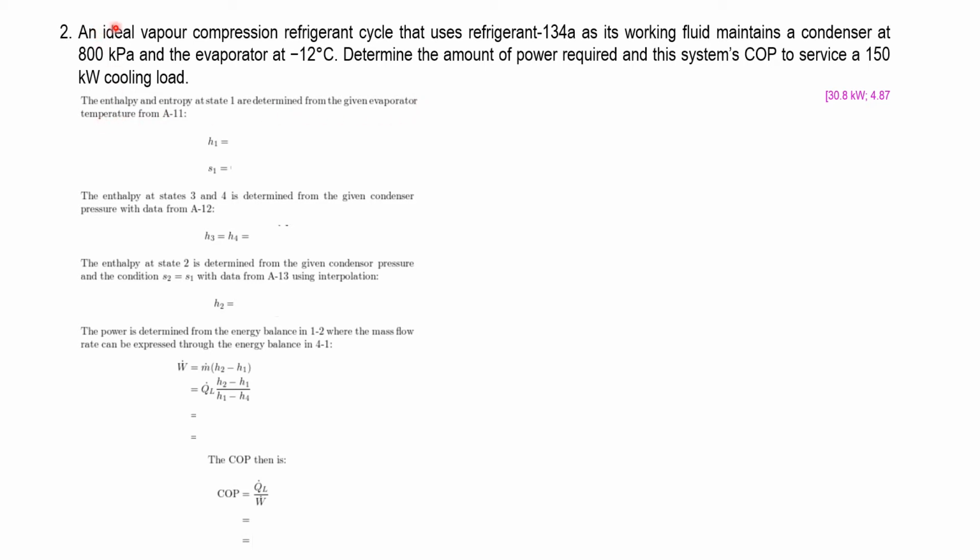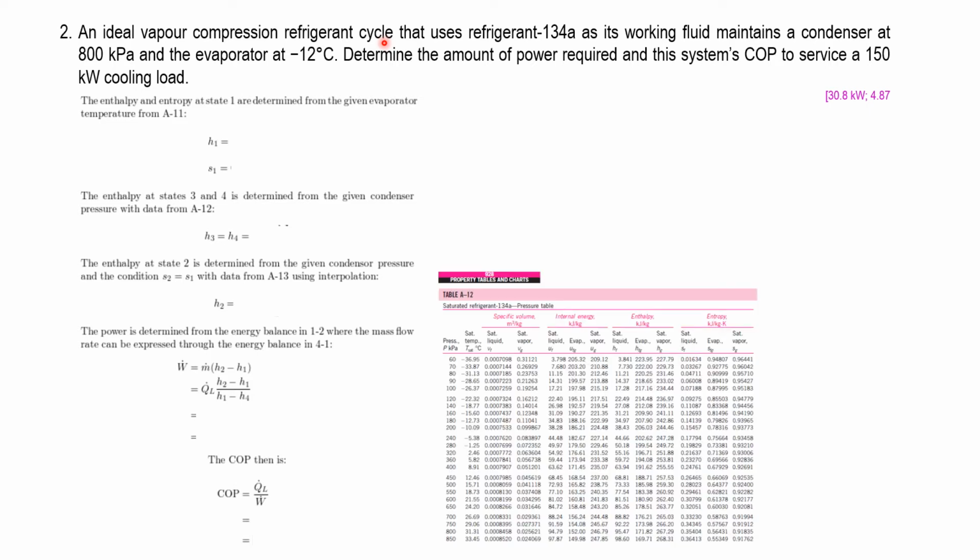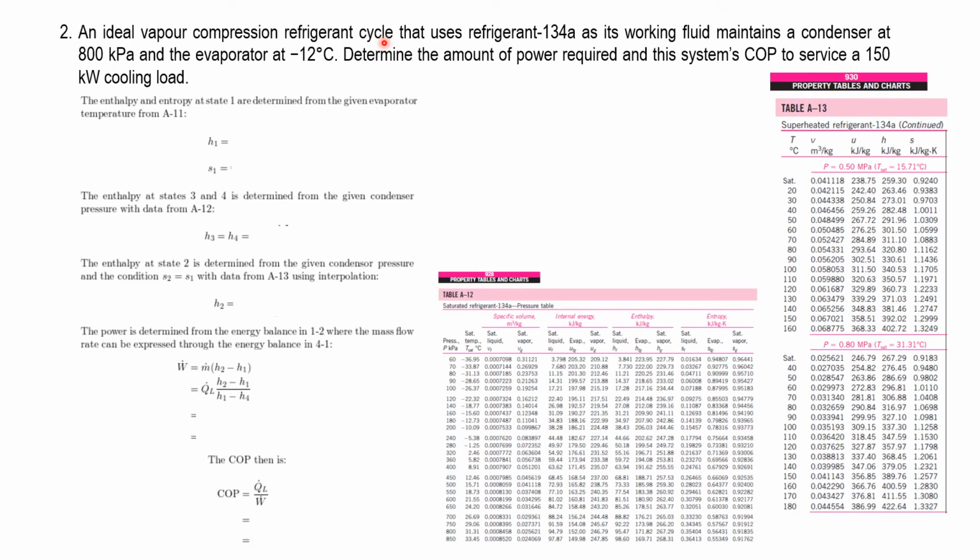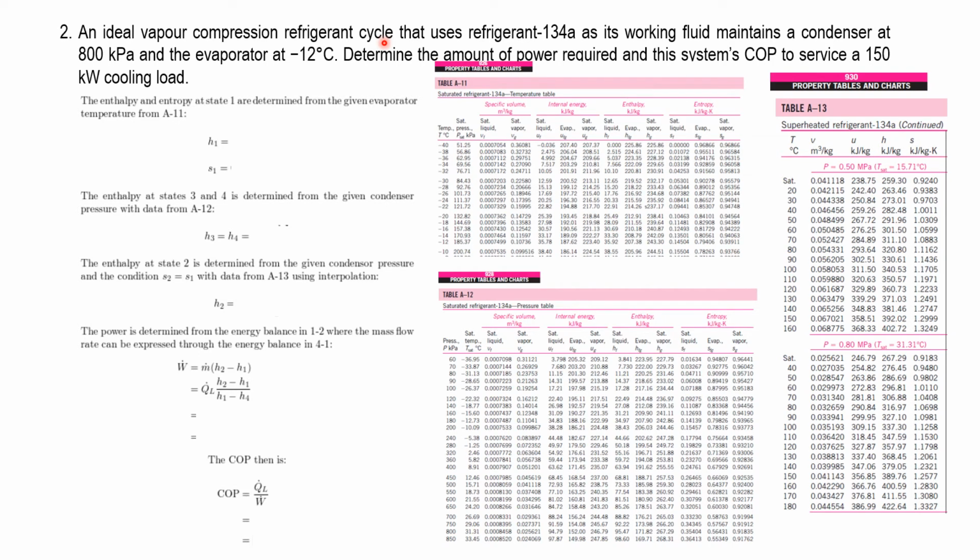Now look at the evaporator temperature. Here we have evaporator at -12 degrees C, right? This is again ideal vapor compression refrigeration cycle, right? Based on your TS diagram, you should be able to refer to your tables as shown here, right? So this is for H1. H1 is always at saturated region, right? But it's at the vapor. So we will go to the temperature table now, right?